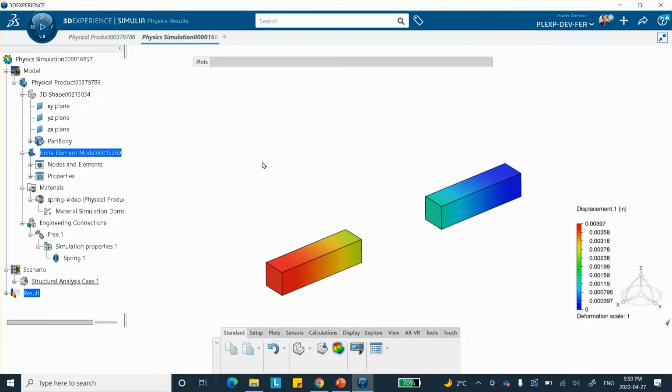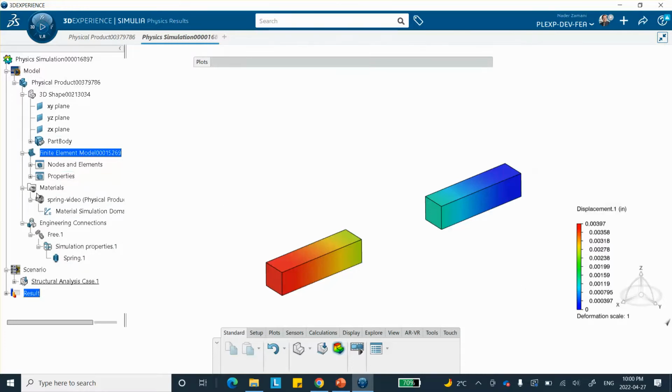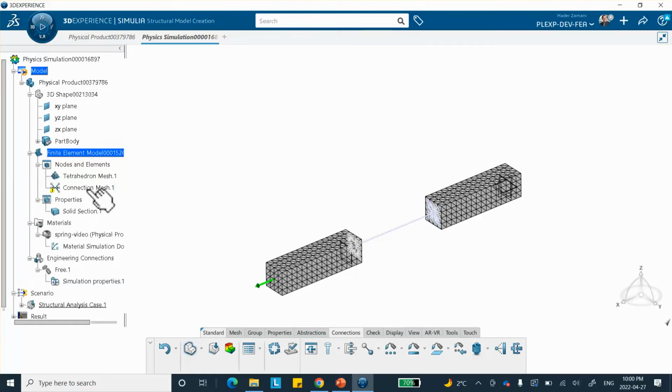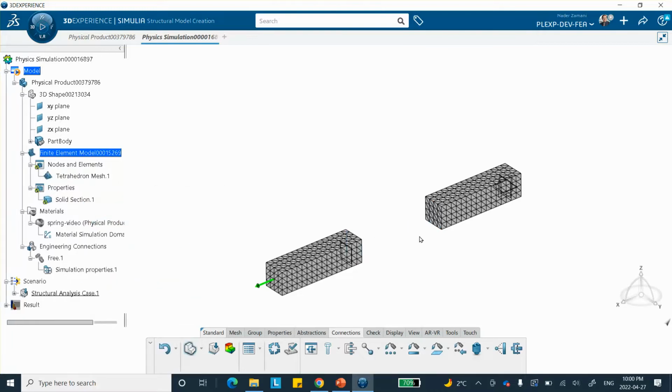Okay, so what I'm going to do now is delete the spring. Let's go back here. Let's go back to model. Okay, so we had this spring. I'm going to delete it. And I'm going to delete that connection right there that is created because of what we just did. Delete this. I'm going to replace it with four springs of 1/4 of the stiffness that we had.